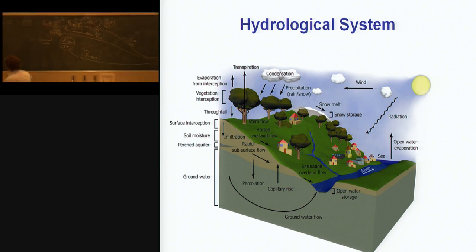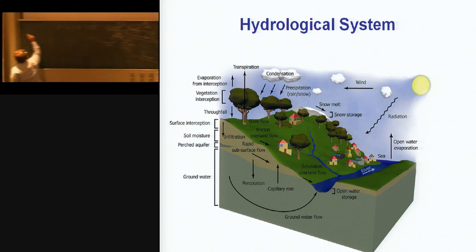Therefore, we can write down this water balance equation a little bit more in a sophisticated way. So the precipitation equals the evaporation plus the runoff plus the dS/dt, same equation again. So precipitation equals the ES, yeah, the soil evaporation or surface evaporation, the evaporation from the interception storage, EI, plus the evaporation from the plants directly, that's the transpiration.